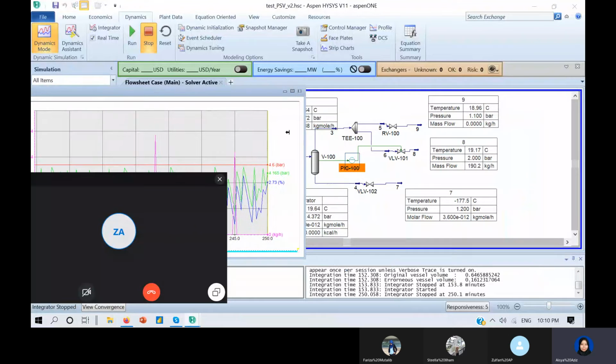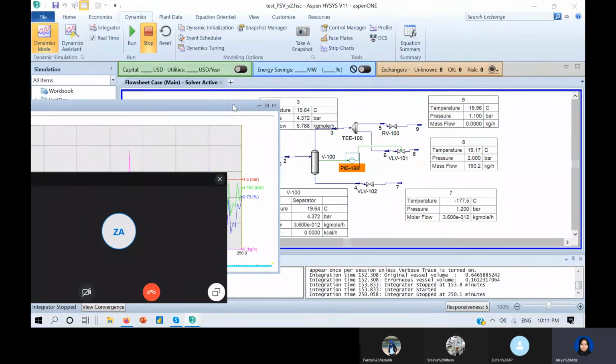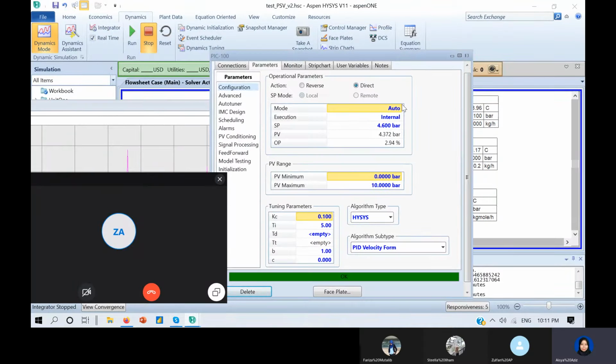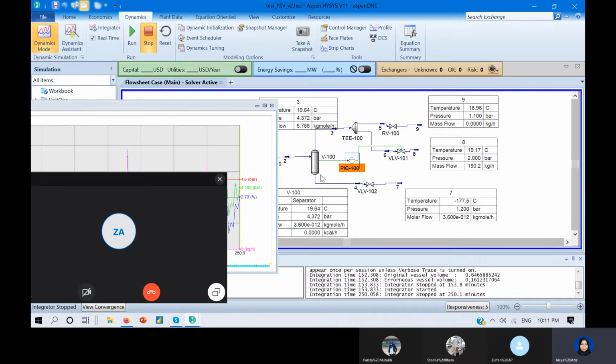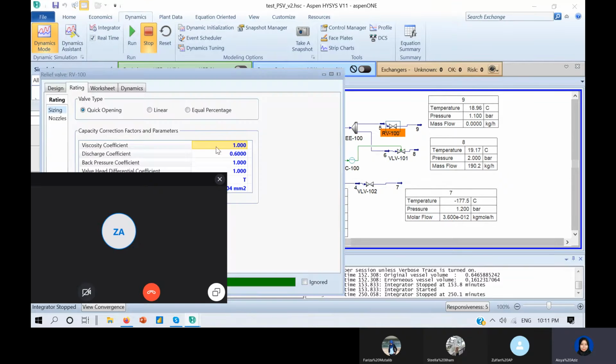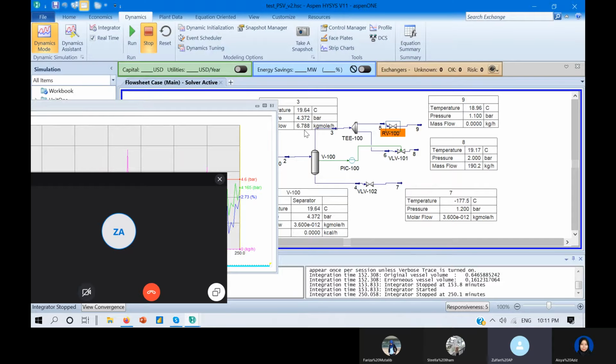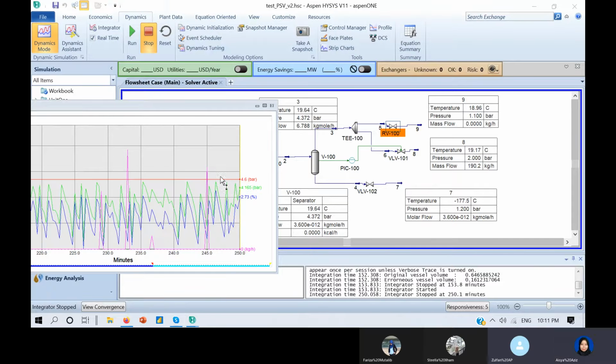You see, we have a pressure valve here that was set at 3.5, and so this pressure vessel did not actually reach the 4.5 which it was set to.